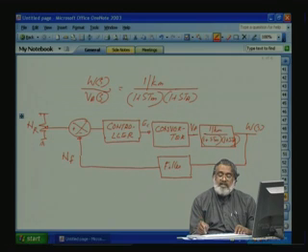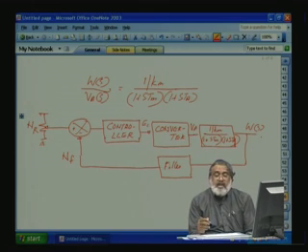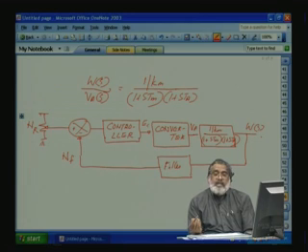We are only looking at the speed and the voltage. But what is the machine current requirement? For a machine there is not only the voltage rating, there is a current rating also, maximum current rating, or short time overload. We cannot exceed that.